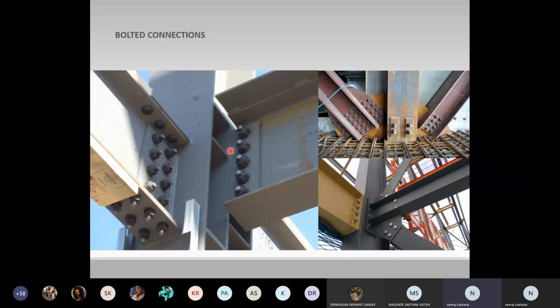The alternative arrangement of structural members is also possible if required. We can easily remove the nuts and change the structure if at all required later on, and it is easy compared to rivets. A lesser working area is required, since there is only a person fixing the bolts. It does not require any heating mechanism as with rivets.